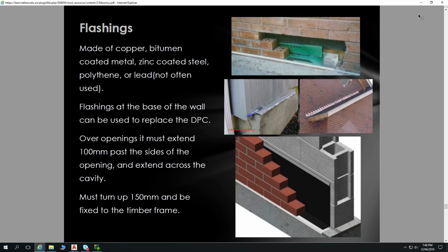So over openings, the flashing must extend 100 mm past the side of the opening and extend across the cavity. It must turn up 150 mm and be fixed to the timber frame.